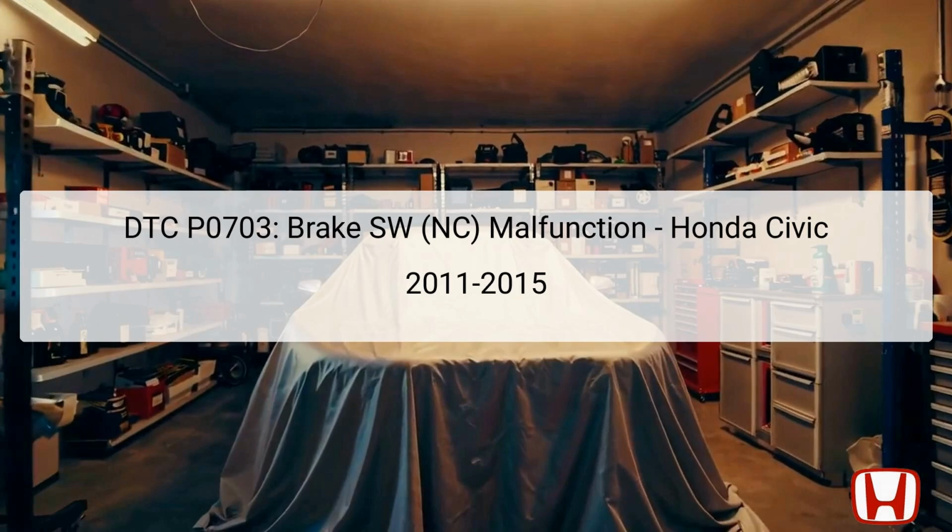DTC P0703 refers to a malfunction concerning the brake switch NC, normally closed, for Honda Civic models from 2011 to 2015. This code indicates that there is a problem with the brake pedal position switch signal, which affects the vehicle's ability to control systems like cruise control and idle-stop functionality.